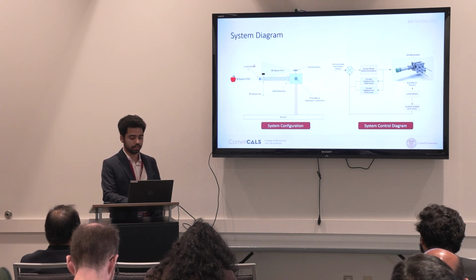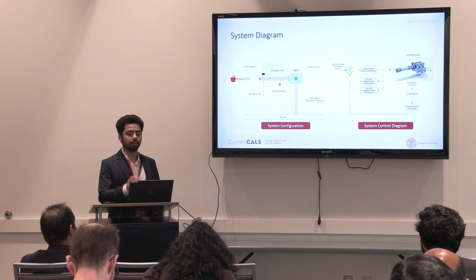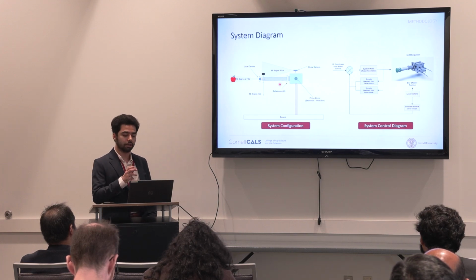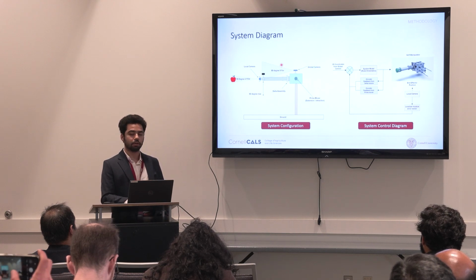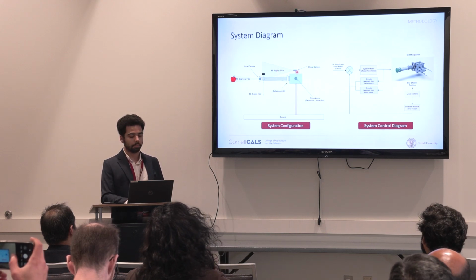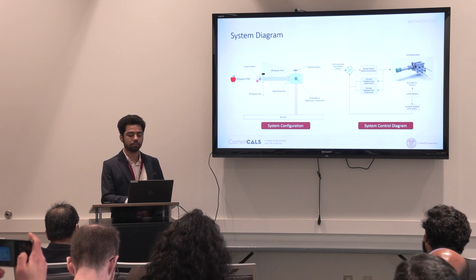This weird thing is kind of like the manipulator. We will see in the pictures how it looks. But essentially this gray thing is a retractable pneumatic fabric based extending arm which has 4 degrees of freedom. It has one camera here and another camera at the hand where an end effector needs to be attached.